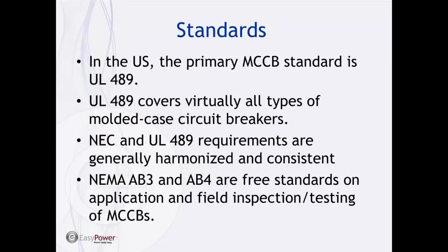UL 489 is not a free standard. You would have to buy that, and it's quite a big standard. But the requirements, you can usually get access to the basic requirements in UL 489 from the different manufacturers of breakers. There are two free standards from NEMA, AB3 and AB4. AB3 covers the application of molded case circuit breakers, and AB4, which we'll talk about a little bit later, talks about field inspection and testing of molded case circuit breakers.